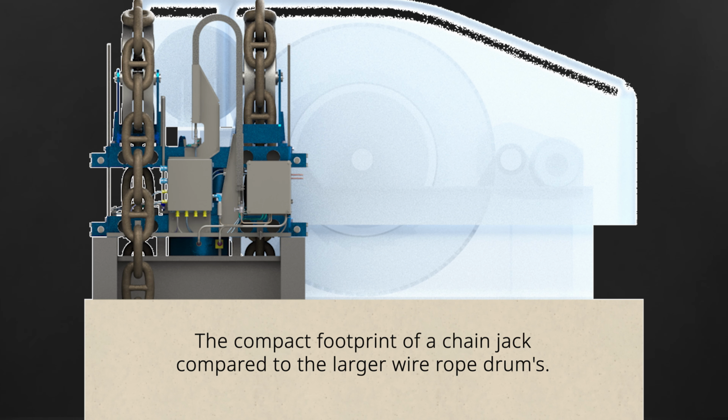Bardex chain jacks are designed with redundant load connectivity. Each chain jack is fitted with 2 chains connecting the lifting device to the ship lift platform. Each chain is sized for 150% of the load.